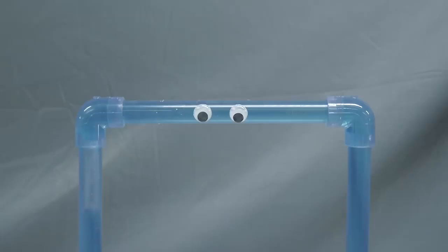This one's a little easier to answer. Because gases are so much less dense than liquids, they almost always float. That means any high spot in a pipe is susceptible to trapping bubbles. And unfortunately, avoiding these high spots is often easier said than done.